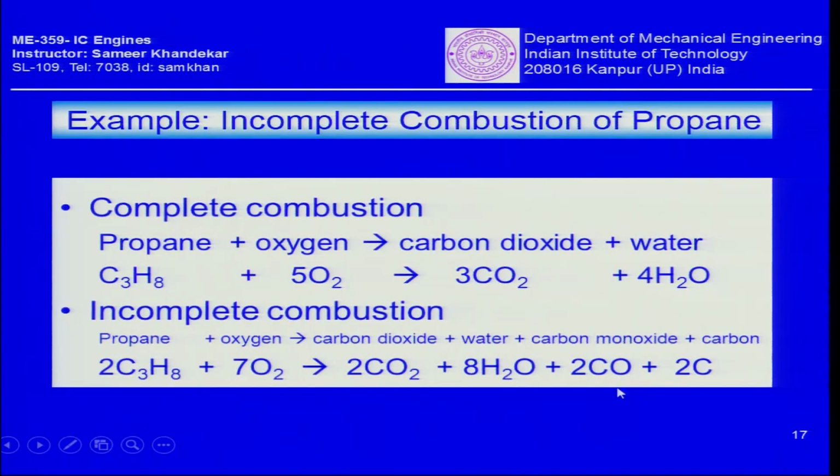That means you may see some carbon monoxide in the exhaust or some soot particles may come out. How do you know what is coming out is very difficult; it's not a straightforward calculation because a lot of chemical reaction kinetics is involved, the time availability is involved, and then of course transport phenomena is also responsible for freezing a particular reaction or starting a dissociation reaction, for example at a certain temperature. So several things are responsible which will lead to a situation where incomplete combustion takes place.